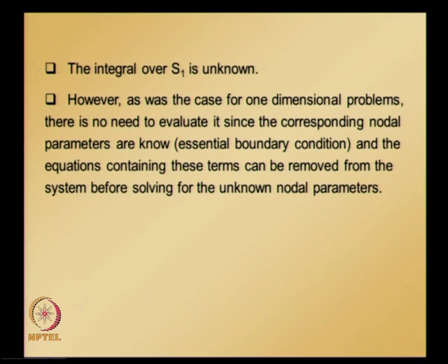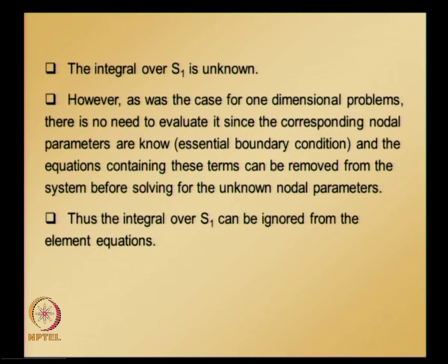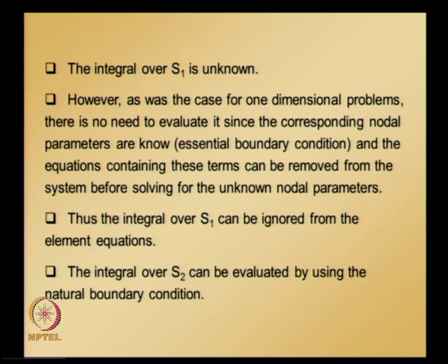However, as was the case for one dimensional problems, there is no need to evaluate integral over S1, since the corresponding nodal parameters are known, essential boundary conditions are specified, and the equation containing these terms can be removed from the system before solving for unknown nodal parameters. And this is what we did even when we were deriving the element equations for one dimensional problems. Thus, integral over S1 can be ignored from the element equations, and the integral over S2 can be evaluated using natural boundary conditions. So, this is the reason why the integral over S is replaced with integral over S2 in the second equation.